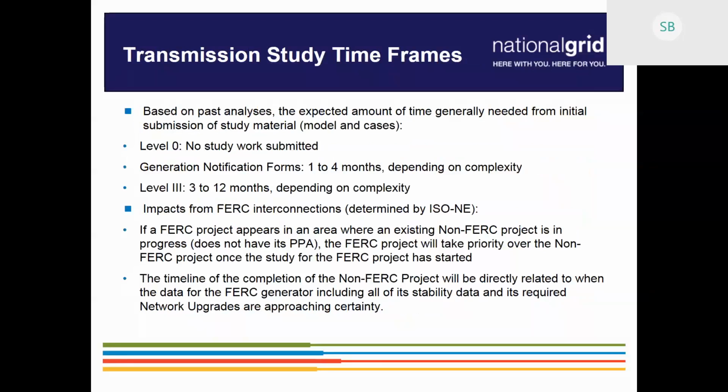Other thing I forgot to mention is that today ISO hasn't asked us for the individual interconnections to provide PSTAT testing. However, that's another type of testing that is at the discretion of ISO, and that it will require the customer to provide the PSTAT models. But we will let you know as specific to the respective interconnection as we learn more from ISO New England.